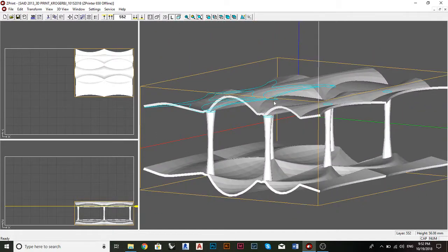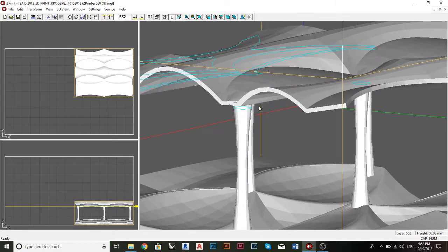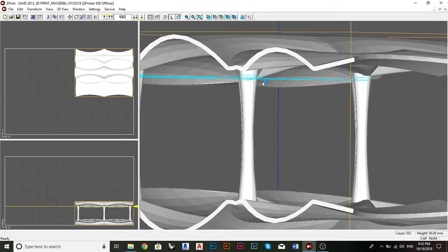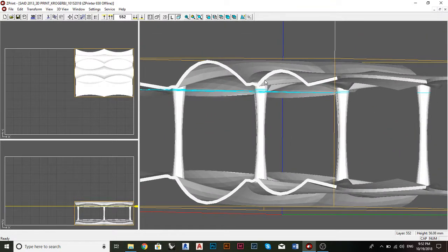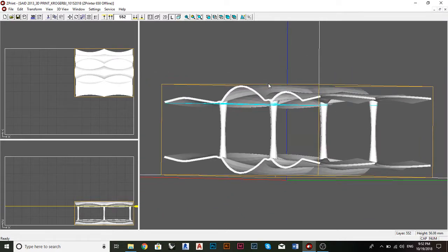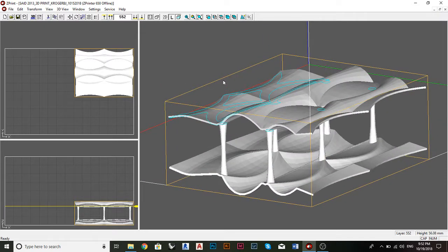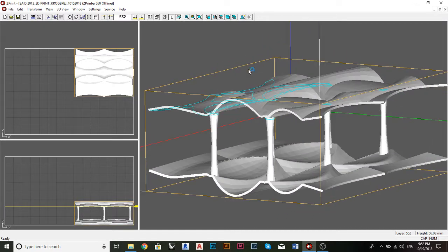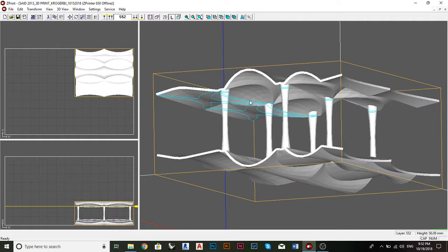In Mara's tutorial video, she actually shows you how to make a mesh. That is one way of testing whether or not your file is good. But you do not need to export a mesh to STL in order to 3D print. You are more than capable of 3D printing a poly surface that has the same properties. It's a watertight solid and has no non-manifold edges. So you do not need to do the mesh step. If that seems confusing to you, don't do it.